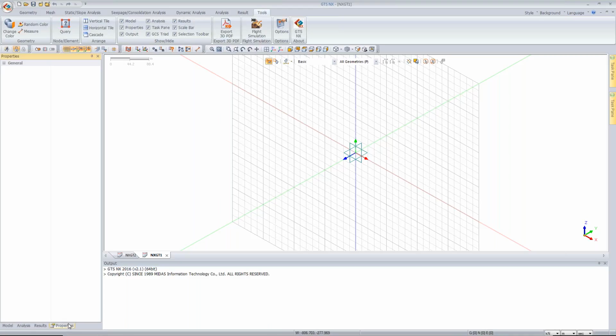Properties are basically when you want to check the property of any selected item, you can go to properties and check for that. Even if you want to control the displacement contour or the deformed shape, there are some default amplifications given. For example, if the deformed shape is too amplified for you, you can go there and change the values. Fine. You have the work tree window, and at the bottom you have the output window. Now, as we move on, I will highlight various important factors. But first of all, let me talk about the work plane.